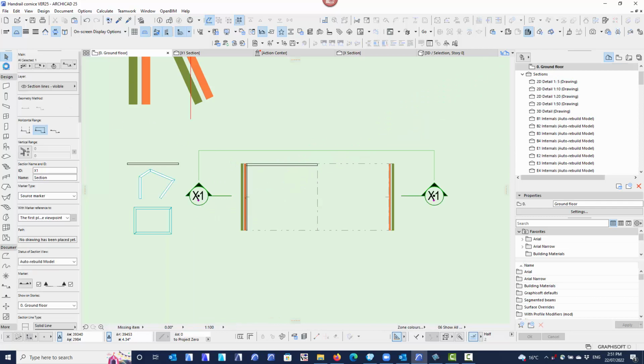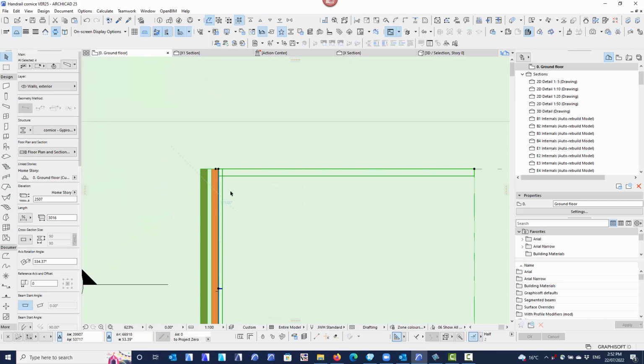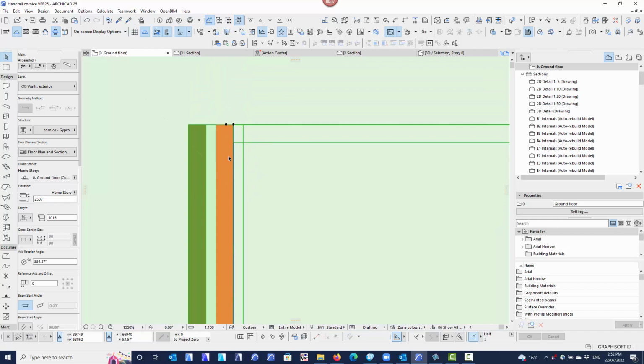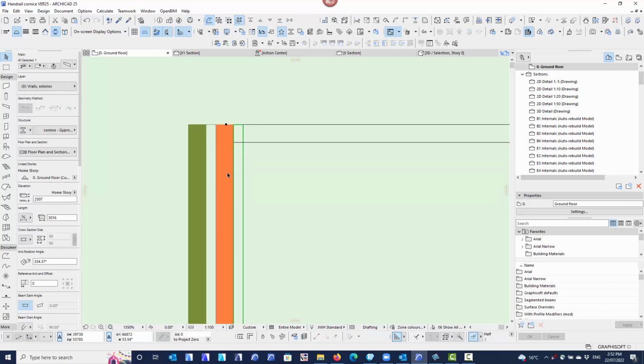Now the other problem is the corner. Now that we've dragged that cornice, when I select this, this cornice now has moved, so in plan it looks incorrect. Well, it's not really incorrect. The axis line is this point here. So for this cornice, the axis line is going through here. We've moved that, and the cornice is literally that deep now because it's on an angle. Remember, we've rolled it to suit the angle of the ceiling. But because we've moved it across, the axis line has come across to here. This cornice here, the axis line is still there.